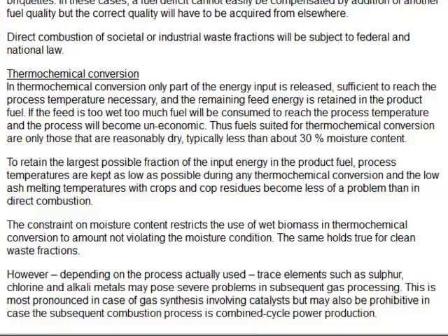This in turn leads to that the input, the feedstock, must not be too wet. Because if the feedstock is too wet, then first your heating value is low, and second, you have to use a lot of the energy only to boil off water, and that will render your thermochemical conversion process very, very inefficient.